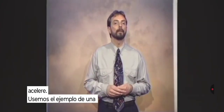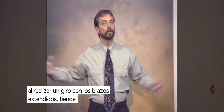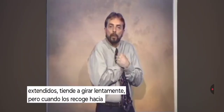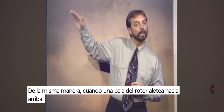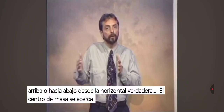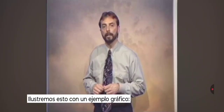Let's use the example of a figure skater to show this. While performing a spin with her arms extended, she tends to spin rather slowly. But when she draws them in towards her rotating body, she begins to spin faster. In the same way, when a rotor blade flaps up or down from true horizontal, its center of mass moves somewhat closer to the axis of rotation, and the blade accelerates. Let's illustrate this with a graphical example.